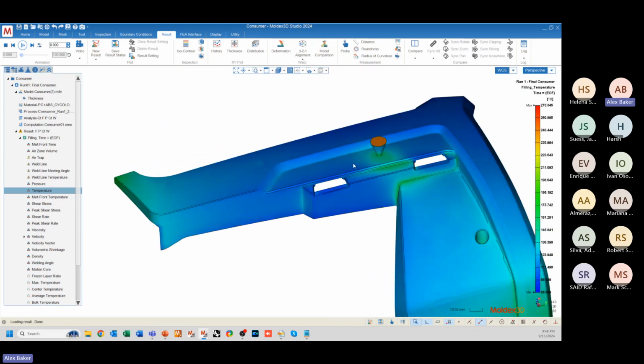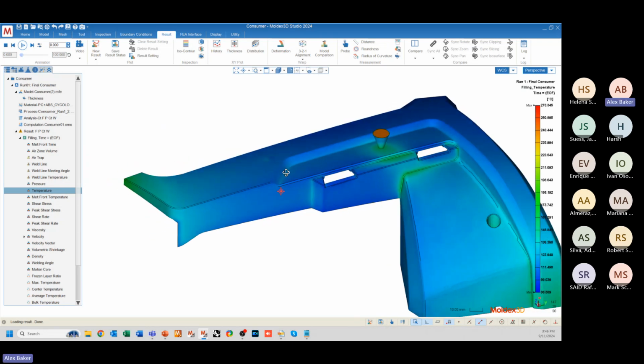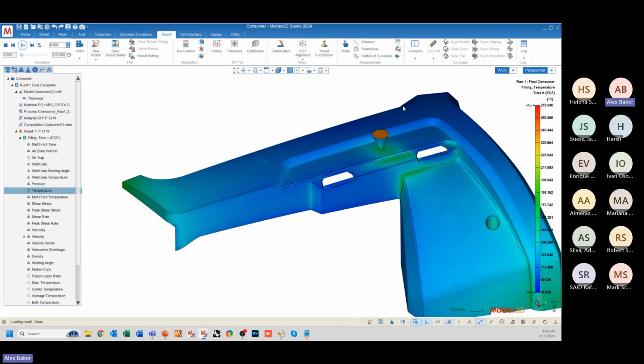And that will actually tend to increase the temperature of the melt as it progresses. So there's actually this balance that's occurring. Energy is constantly being released out into the mold, but the movement of the material is also converting that energy into heat. So there's a heat generation effect, and then there's a heat release effect. I usually like to call it the cooling effect and the shear heating effect for simplicity.